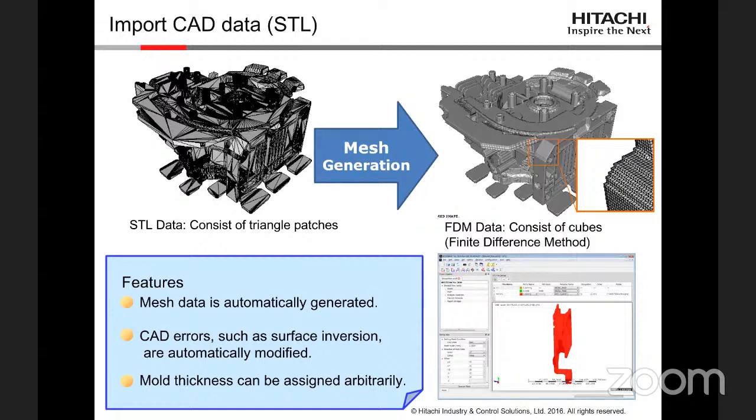If we provide a mesh size of 1 mm, then it will take 1 mm gaps and convert all the body into elements in order to do the simulation at every point.